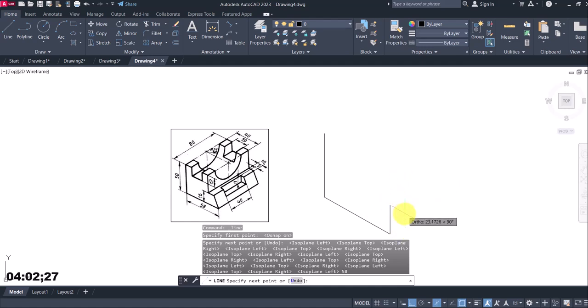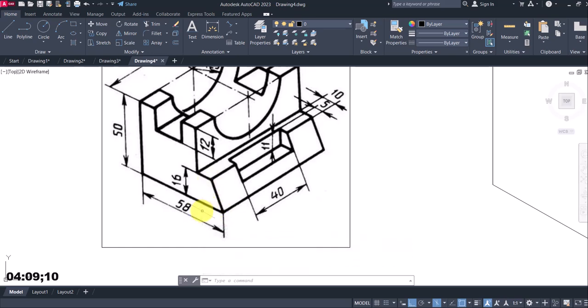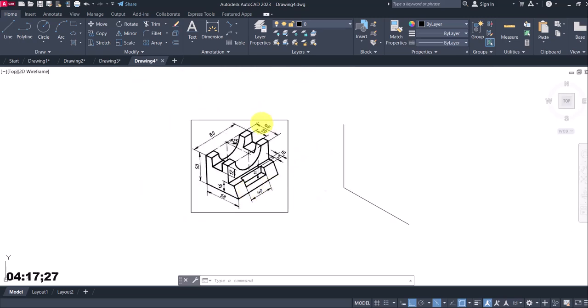Okay, now the next step on this drawing is to draw this particular line, but this line is not in isometric direction. It is not 30 degrees to the horizontal. So now I'm going to terminate at this point. I'm going to navigate to the other end of the line, then I'll connect. All right, so line again. With my object snap, I want to continue from here.